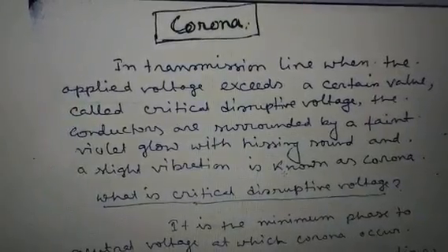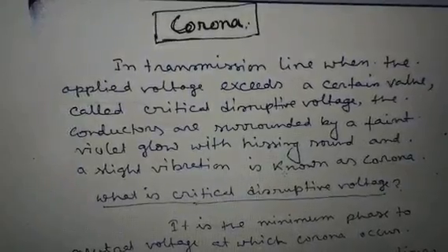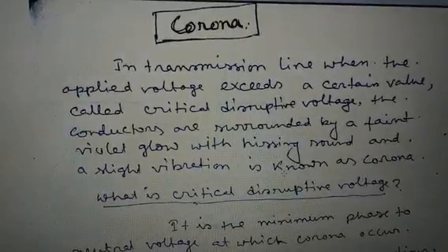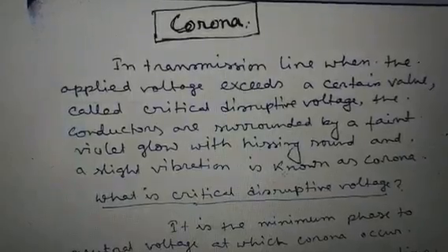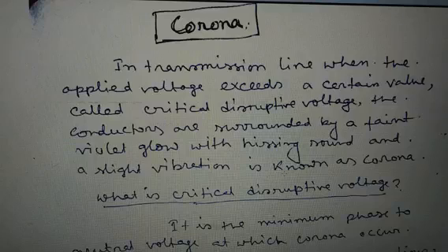If the conductors are polished and smooth, the corona glow will be uniform throughout the length of the conductor. Otherwise, the rough points will appear brighter. With DC voltage, there is a difference in the appearance of the two wires. The positive wire has a uniform glow about it, while the negative conductor has a spotty glow.